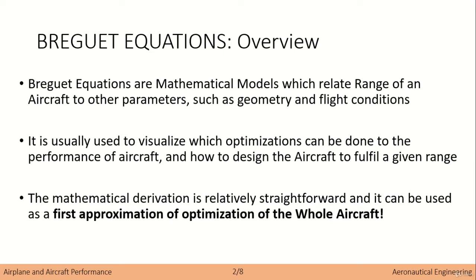Now, let's start. Breguet equations are mathematical models which will relate the range of an aircraft, so the distance an aircraft can travel, to other parameters, such as geometry of the wings and flight conditions, for instance. It is usually used to visualize which optimizations can be done to the performance of the aircraft, okay? And how to design the aircraft to fulfill a given range.